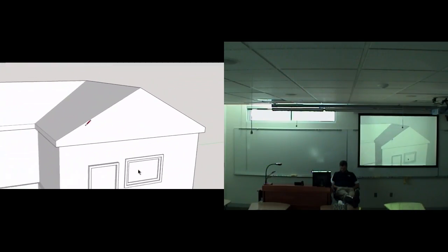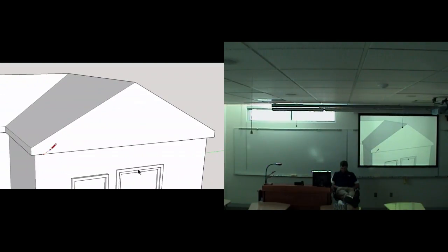Use the line tool and start drawing a line from this edge. Now hover over the roof edge for a few moments, and as you continue to draw, you'll see a new inference that is purple in color and parallel to the edge we just hovered over. We can easily find out how far to draw this parallel edge by hovering over the ridge point to focus attention there. Then, as we come back to drawing our original line, SketchUp will tell us where these points meet.